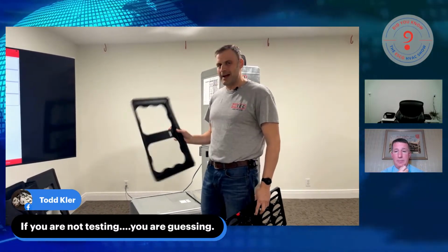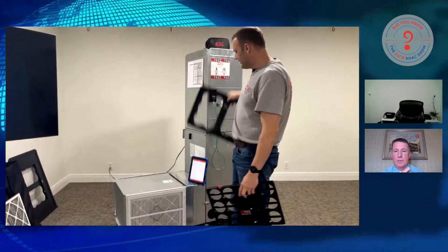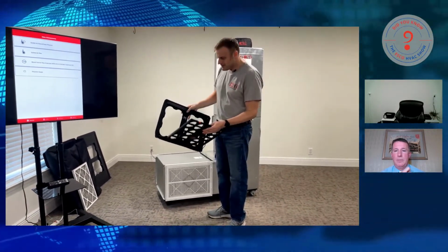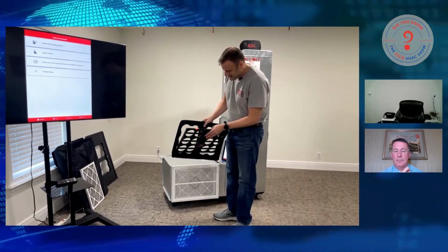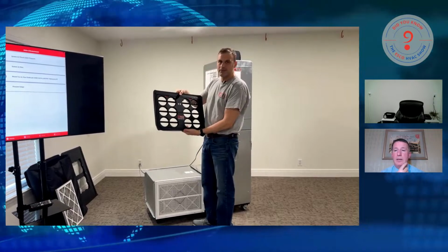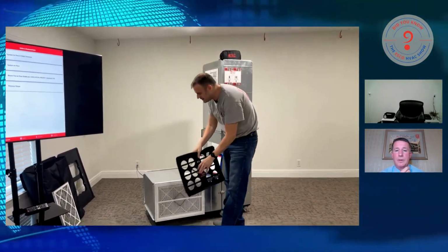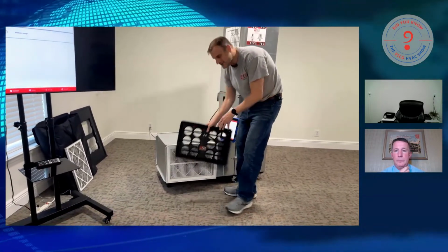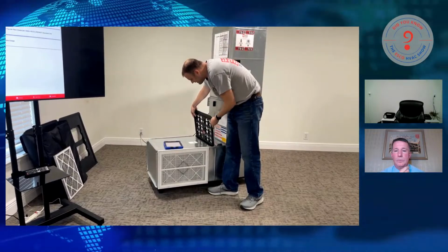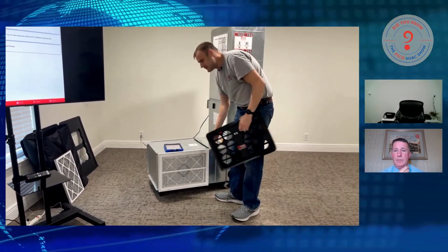This is an adapter plate. This is our 14 by 20. It's our smallest plate. This demo unit is one I break down and take to conferences to train on. But this Trueflow snaps into the adapter plate like so. The adapter plate is gasketed to make a good seal when it goes into a return air grill. It could also fit in a return air slot. So it can be used in a slot, or in a filter grill.